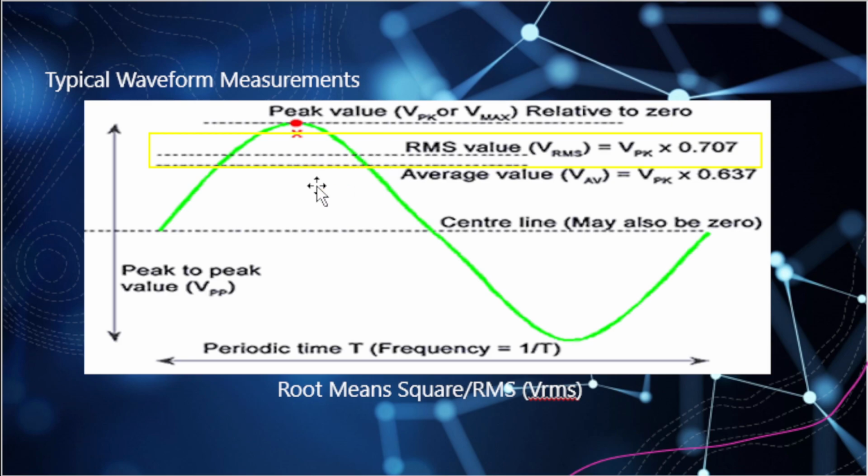So how is this applicable to us between all these different types or forms of measuring AC? Well, generally speaking, your technical data, or your technical guide, or whatever you're using in order to make your measurement is going to tell you what you should be measuring in what format concerning the AC measurement. Meaning, it's going to tell you that you have to measure this value in a peak-to-peak or a peak or volt RMS or volt average fashion.